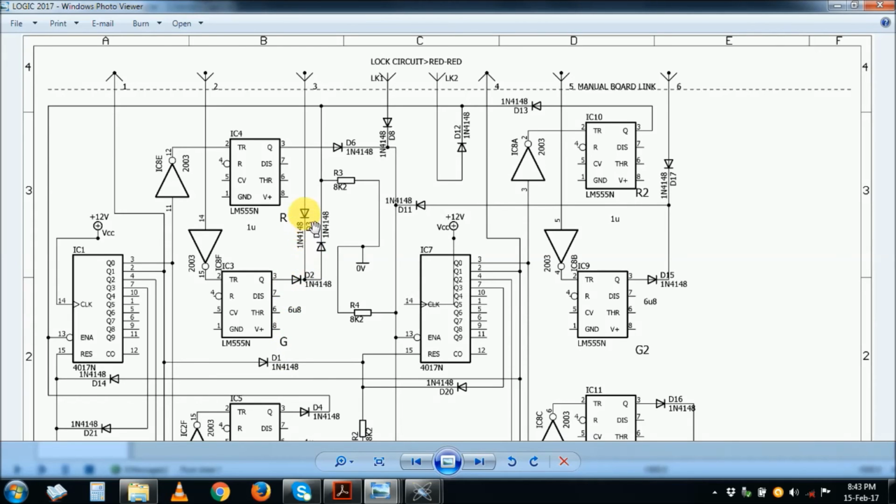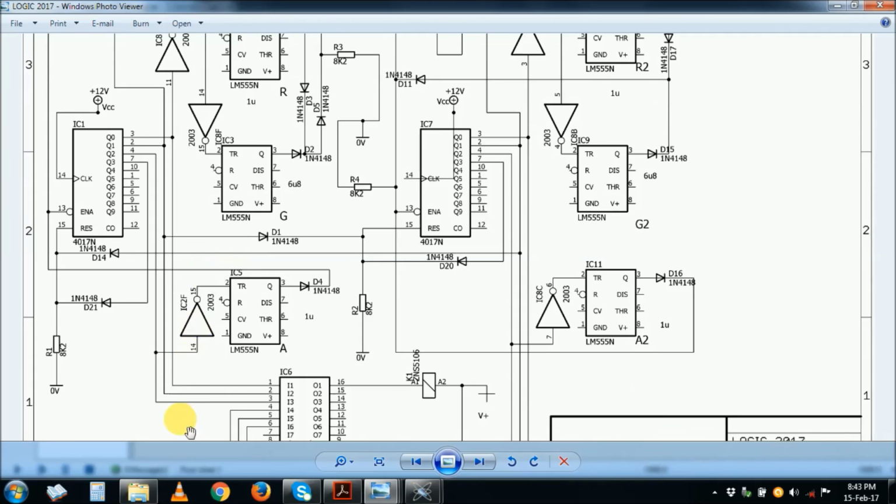Output high goes here, it's blocked, can't go, but here through this diode, here it's just clamp, then goes here, remember diode blocking, and then to enable, remember here it can go blocked again, enable there, and the time duration lapses from the green time from high to low, steps again to number 4. Number 4 is the amber, the same procedure. Amber number 4 drives the amber relay. Number 4 again also comes here to this one, the driver high, and a low pulse comes here to trigger this timer for the amber now, and then this output goes high for the time duration of the amber.